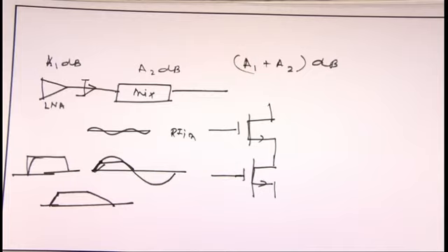So it behaves as a trapezoidal kind of thing, basically a rectangular wave with a finite rise and fall time. So similar harmonics you will get, but at the cost of time, because the finite rise and fall time, charging and discharging, will cause some delay and some distortion.